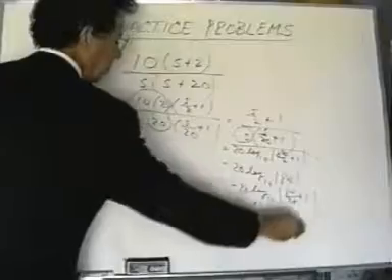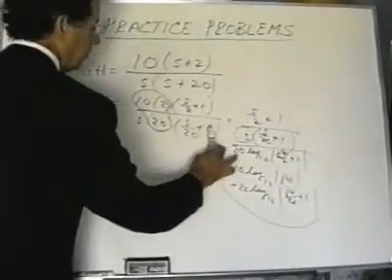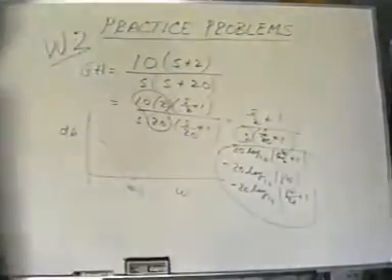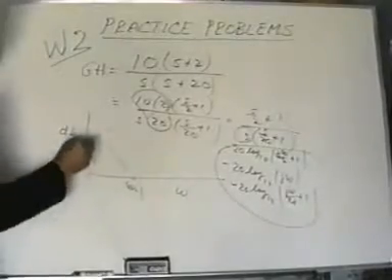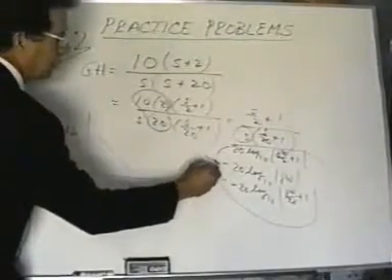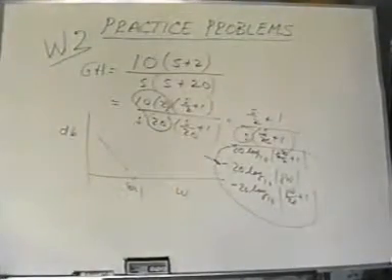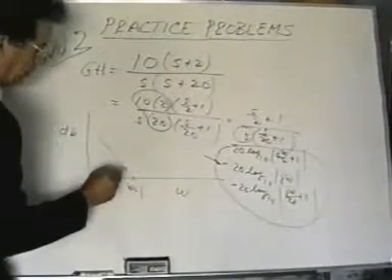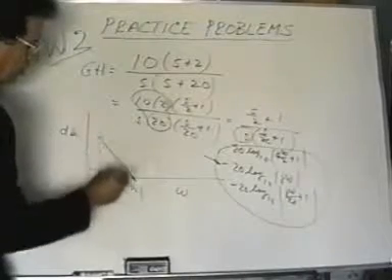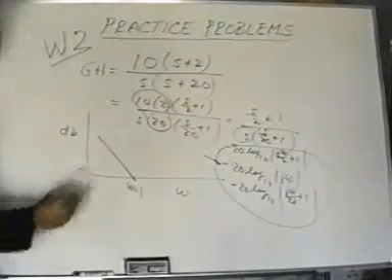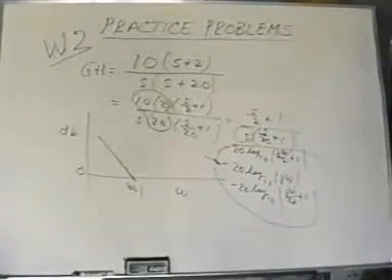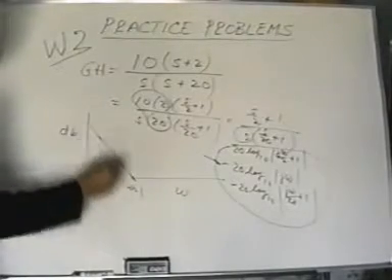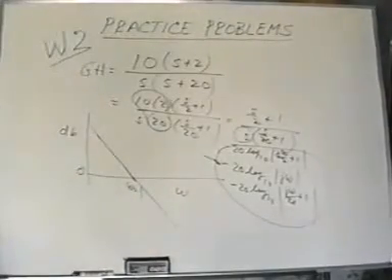So this is really what we're plotting now, because we've now put everything in terms of decibels. And so this term I'm plotting here is really the second term in here. The one that says minus 20 log base 10 of j omega. Forget the j, and that term passes through 0 dB when omega is equal to 1. Now I could extend this line in both directions as needed.